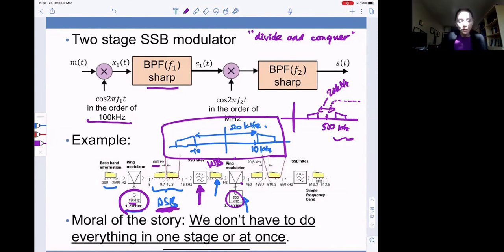When you use a higher frequency carrier, the discriminator filter you use in the first stage is going to have to be a higher quality filter, because the DC null in the first stage is only 600 hertz in this example. So it's a filter design trade-off. I'm sure you solved such problems in your analog electronics course. It increases the cost of the filter.